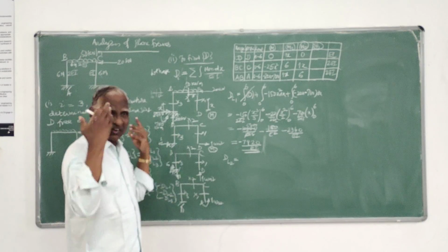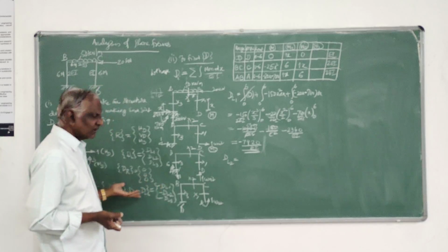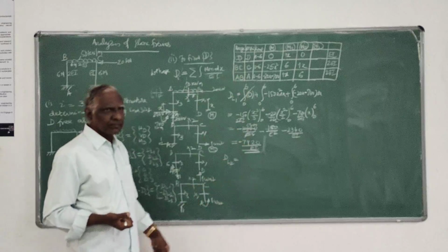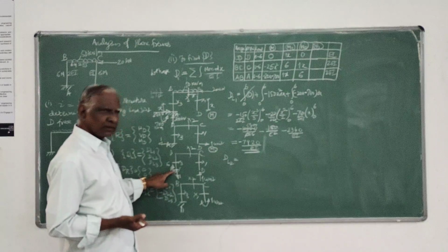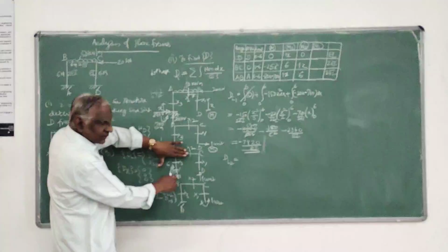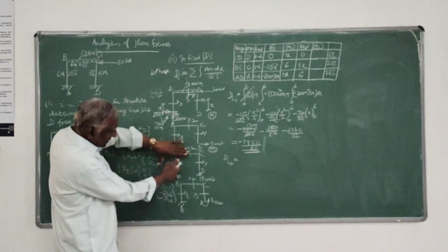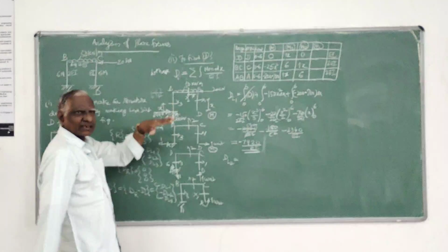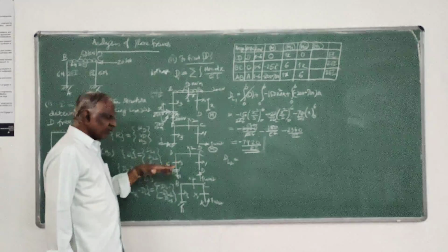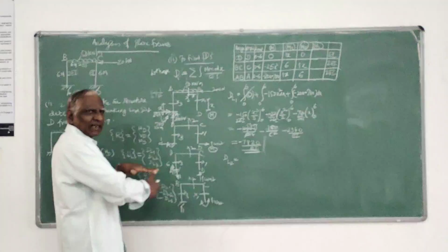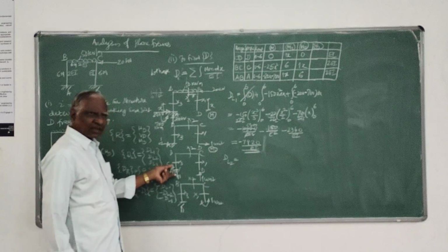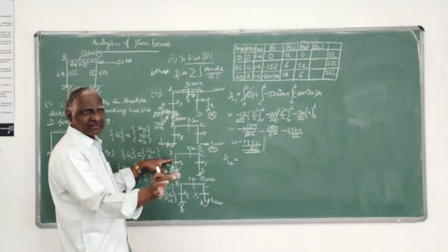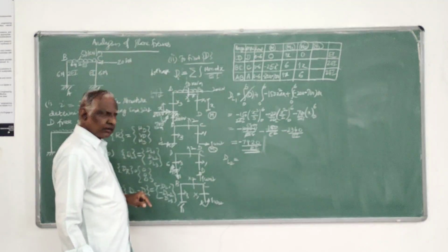This you have already done in lots of problems, strain energy. So the same thing is to be followed. Nothing other than that. So at AB only 6 we have to consider. Here only this moment. This moment remains the same. And because this is a vertical reaction, 0, it passes through that section. It will not give any moment. Moment you will get only when there is a lever arm. It is not there at all. Along the line of action of the force, it will not be at some distance. So we are considering only the span AB.